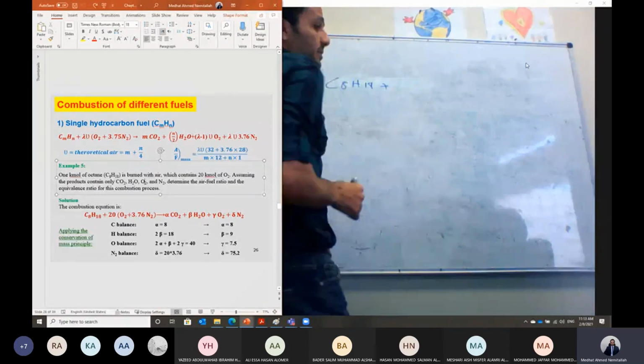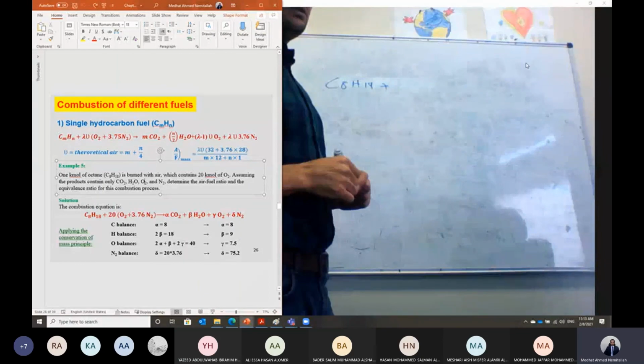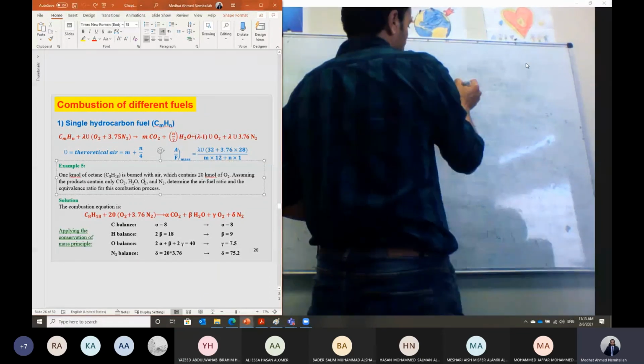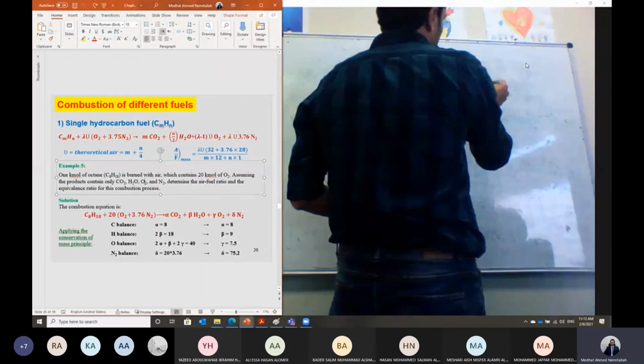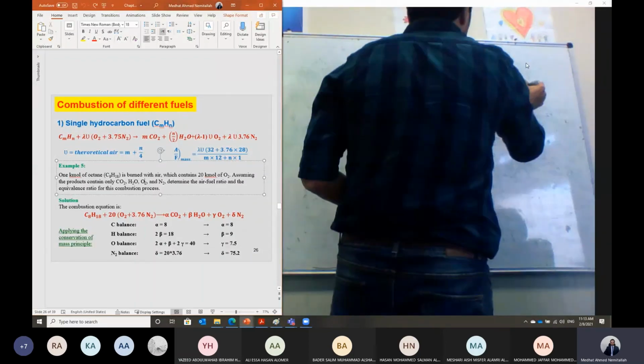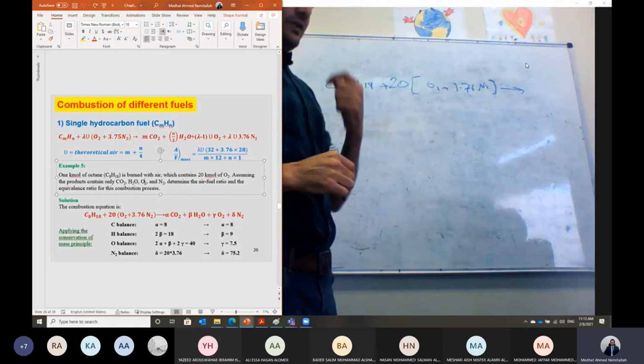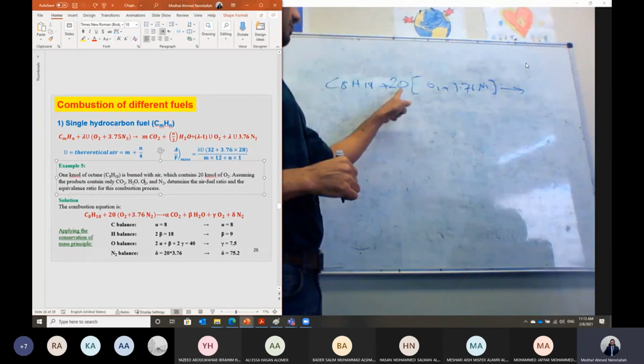Okay. So he said we have isooctane, C8H18, burned with 20 kilomole of air, which is O2 plus 3.76 N2. In this case, he didn't provide us the value of the excess air factor. He just gave us the number of moles of air, and he said this 20 kilomole is burned with 1 kilomole of isooctane. So how can we write down the combustion equation?